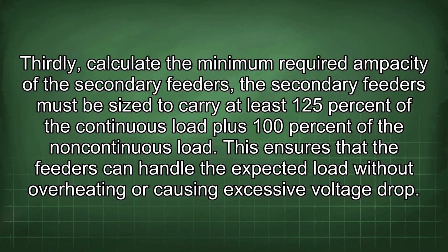Thirdly, calculate the minimum required ampacity of the secondary feeders. The secondary feeders must be sized to carry at least 125% of the continuous load plus 100% of the non-continuous load. This ensures that the feeders can handle the expected load without overheating or causing excessive voltage drop.